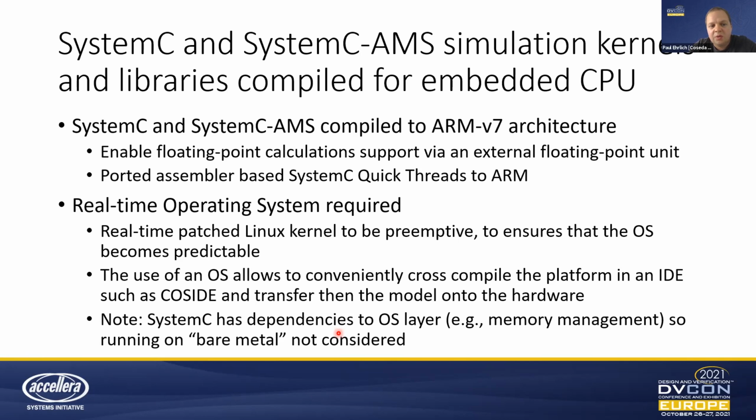So we used a real-time patched Linux kernel in this case. Also, an OS allows you to conveniently access the board via an Ethernet controller, do the model cross compilation on a normal lab computer, and then just send the executable down to the hardware board.